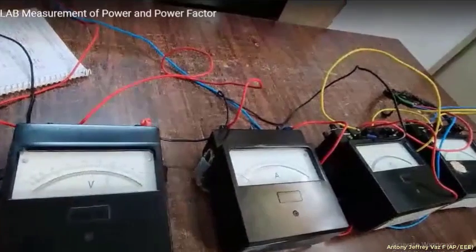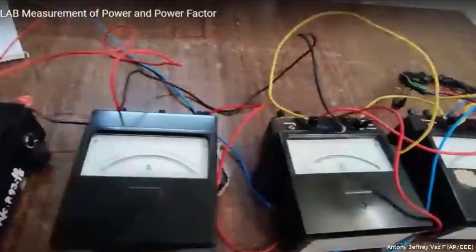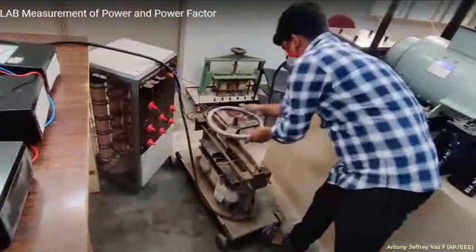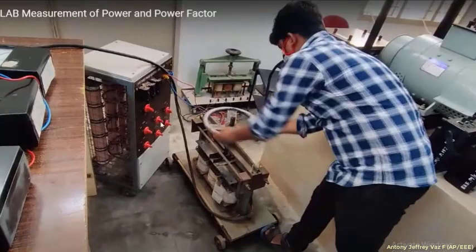You need to change the inductance as you did in the resistive loads, and measure the values here. You can see it clearly. You need to rotate this and change the inductance value, and you can measure 6 consecutive readings, fill the tabular column, do the calculation, and find the power factor of the inductive load as well as the resistive load. Thank you.